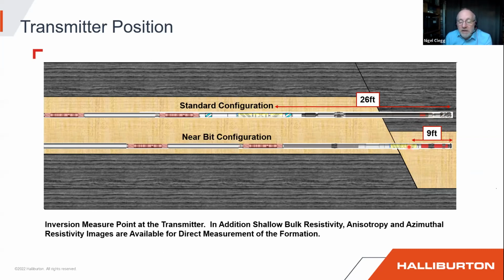Whereas a deep EM tool like this would allow us to see those boundaries away from the wellbore and rapidly identify our positions. You can see the advantage of bringing that sensor measure point and that transmitter forward. And essentially, this is where most of the work with this type of ultra-deep tool is done, is in optimizing the position of the transmitters and sensors, optimizing the frequencies that you transmit at to get a clearer picture of the reservoir, to get identification of boundaries as early as possible,